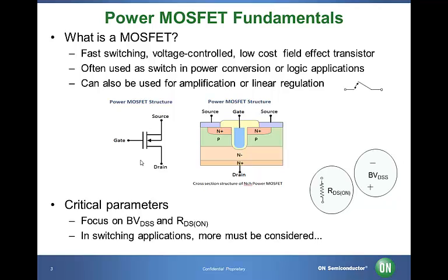If an N channel is located directly under the oxide film of the gate in an N-channel MOSFET, electrons are collected there, and in the opposite case for P-channel MOSFETs, holes, which are an absence of electrons, are generated in the P-channel directly underneath the oxide film. The current flows vertically between the drain and the source. The trench structure makes integration easier and results in a lower on resistance, or RDS.